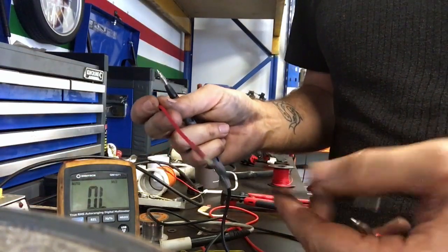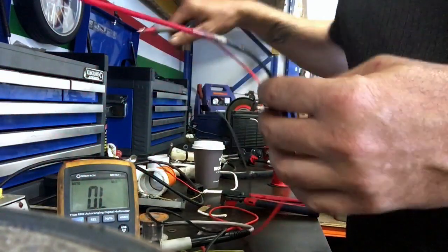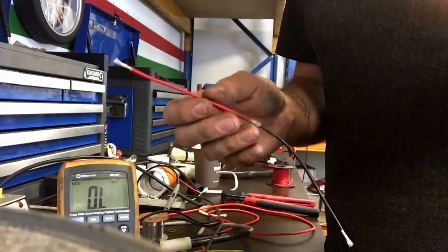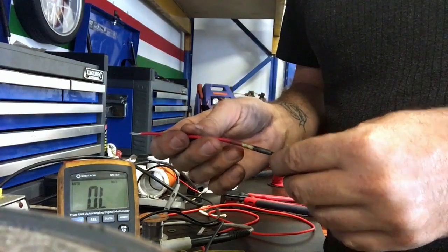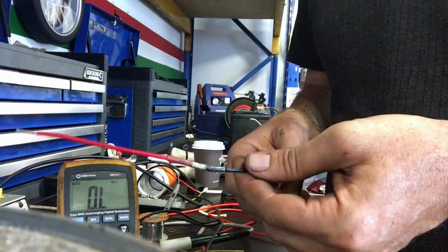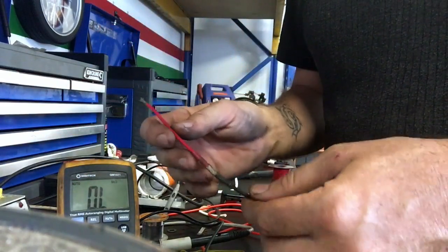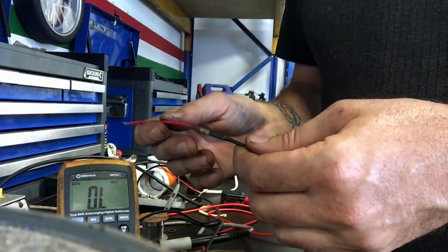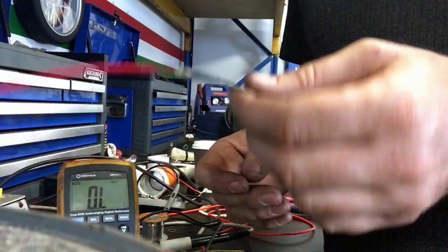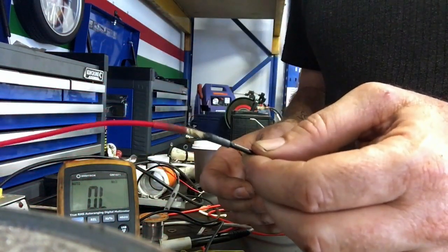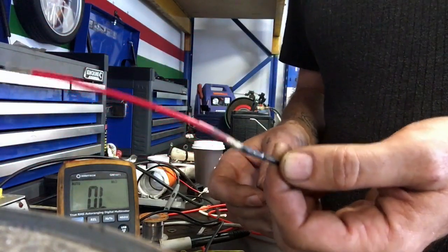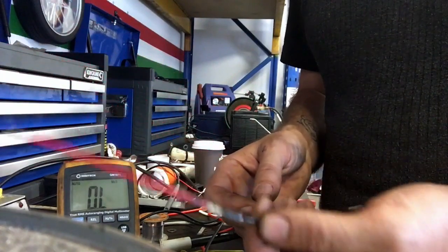I'm not saying that's a startling result, or a surprising result, should I say, but when you look at how much of a voltage drop happened across 220 ohms, you can understand why these bad connections rob the devices on your boat, your bilge pumps, your nav lights, of so much voltage and so much current. So that's why doing these connections properly is important, and using these techniques to find the bad connectors can help you get to the point of having solid, reliable electrics.